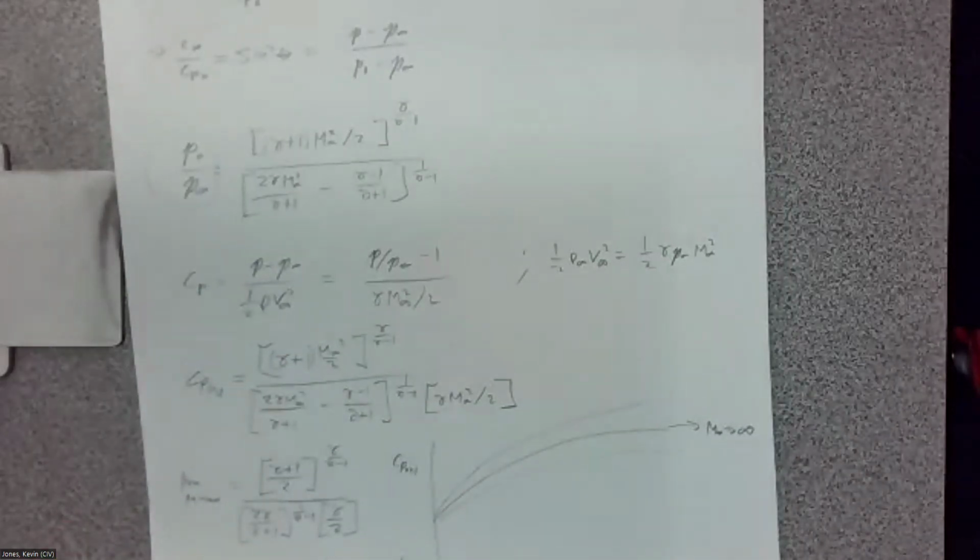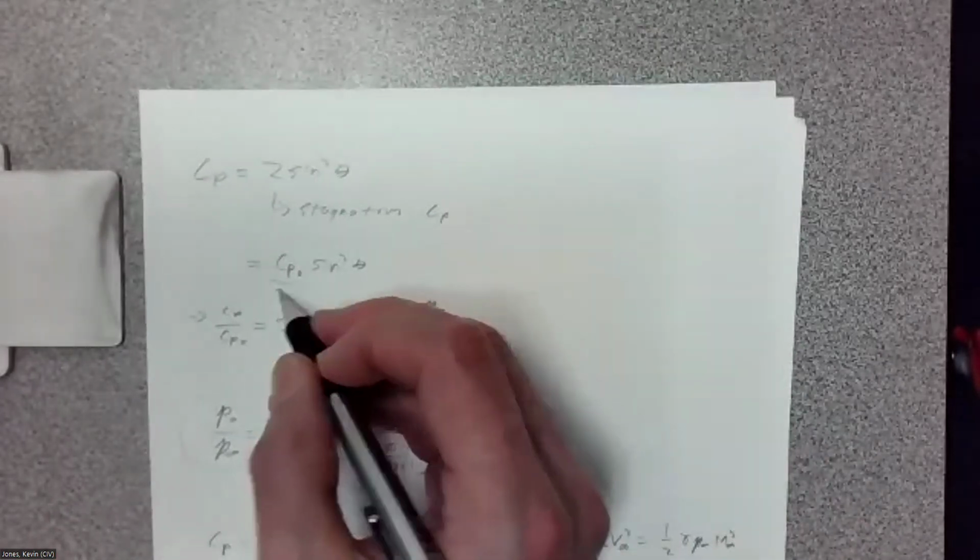All you would do now is take this 1.839 and substitute it back up into here if you want to apply modified theory. And I believe I ask you to do both. The math is trivial, so it takes you 5 minutes less. You'll find, again, the higher the Mach number, the better it works.